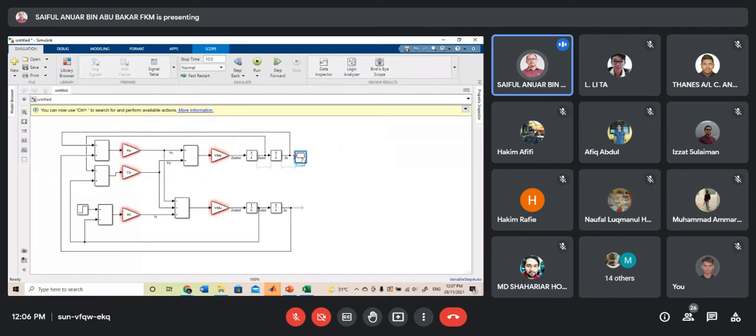Now, mainly we're going to take a look at the displacement. Meaning that if the shock from the road is being isolated by the suspension system, the sprung mass will not move the same way that the road did. Usually, the motion will be absorbed by the shock absorber, and we should expect that the sprung mass is actually oscillating at a lower amplitude.